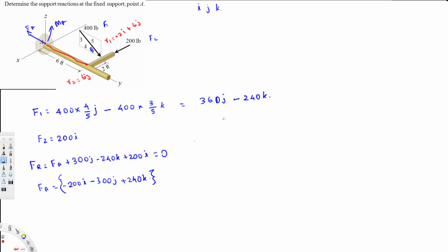So let's see. If I take moment around A, this is positive, and therefore MA is going to be there, and also we are going to have R1. The forces are two different forces. So in this case, we have to do the cross product to calculate the sum of the forces. So I arrange this into ijk order. So ijk. Since we have two forces right here, I have to write it two times, and we are going to add both of them together.